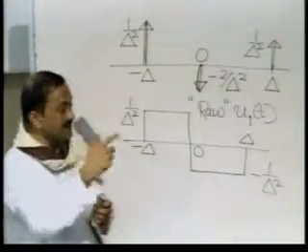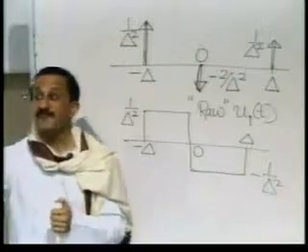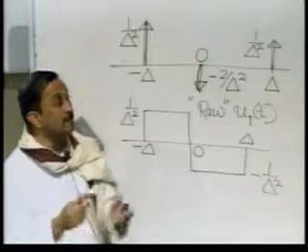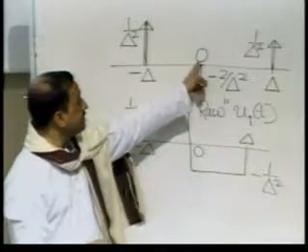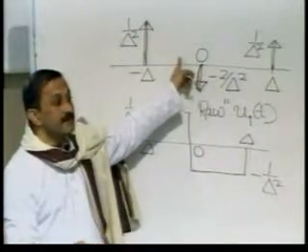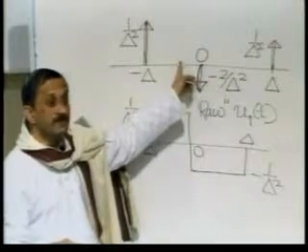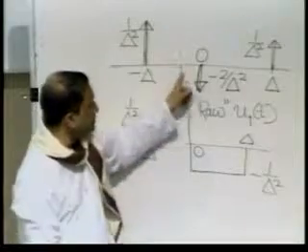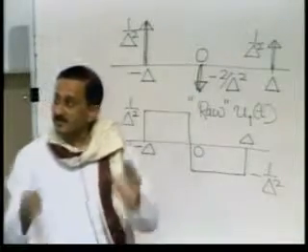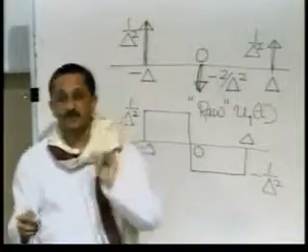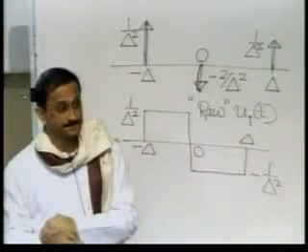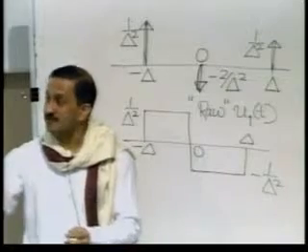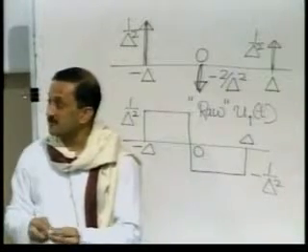So this process can now be continued. Now we get a feel of these objects. So the impulse response of a double differentiator is a limiting situation of this case. Whatever object you get when you visualize delta going towards 0 here is the object that gives you the impulse response of a double differentiator. And similarly, one can have an impulse response of a third order differentiator, a fourth order differentiator, and so on.